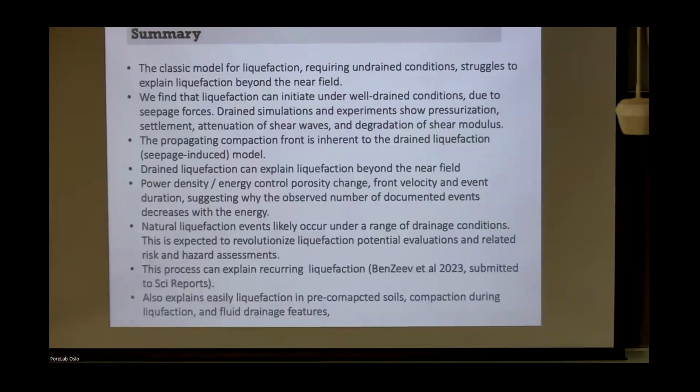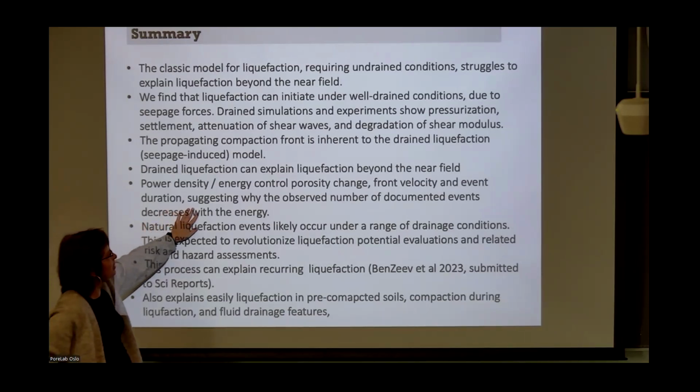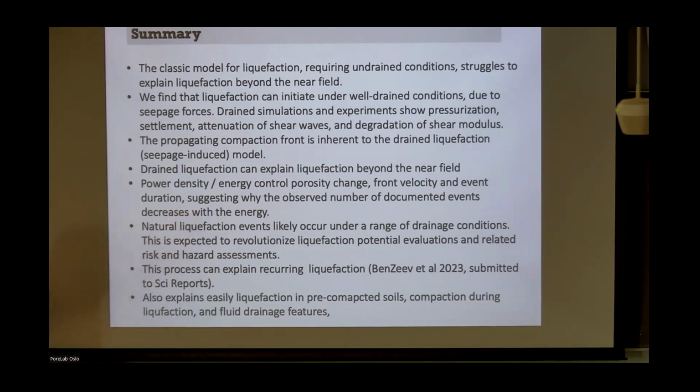Okay, so I'll summarize. The classical model for liquefaction requiring undrained conditions struggles to explain liquefaction beyond the near field. We find that liquefaction can initiate under well-drained conditions due to seepage forces. It shows pressurization, settlement, attenuation of shear waves, and degradation of shear modulus. It has a propagating compaction front, which is inherent to the process. And then power density and energy control porosity change, front velocity and event duration, suggesting why the observed number of documented events decreases with the energy.